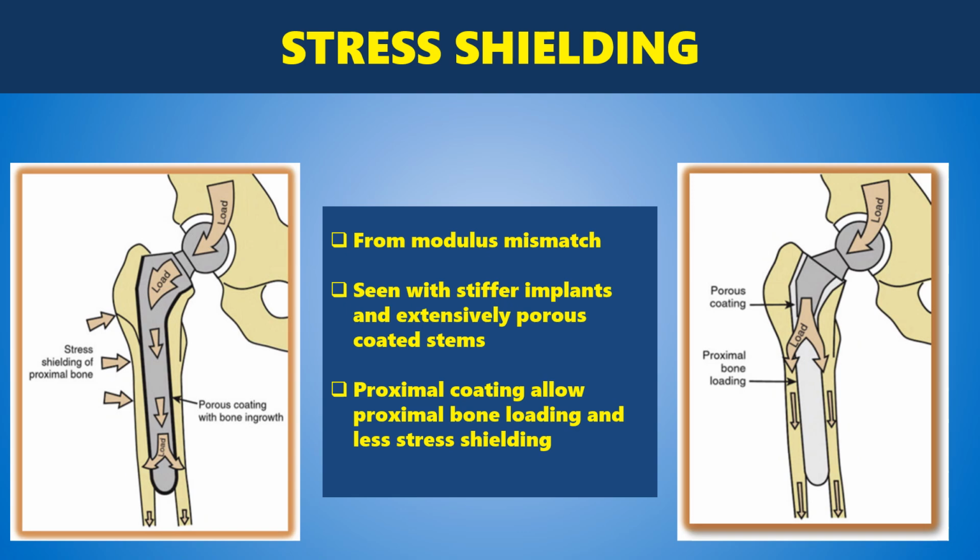Well, in a trauma setting, we usually use intramedullary nails, and the material of the intramedullary nails most frequently used is titanium or stainless steel. It's better to use titanium intramedullary nails because its Young's modulus of elasticity is closer to the cortical bone, so it is a better load sharing device than stainless steel. Why? Because of the stress shielding phenomenon.